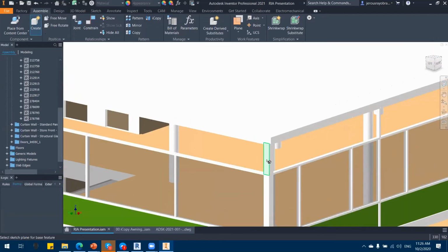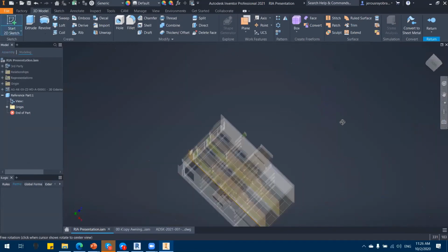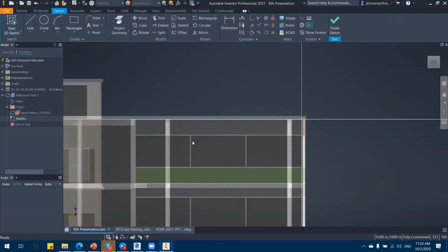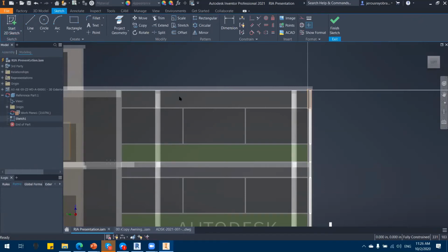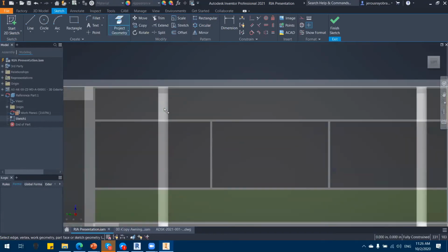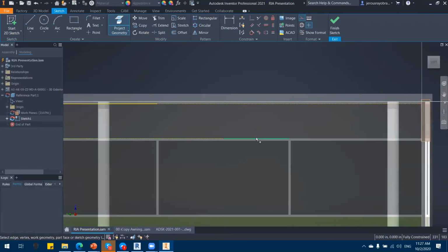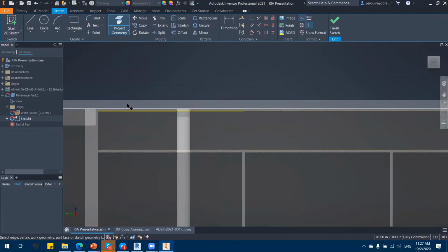In this case here, I'll first create some sketches. I'll create sketches out of this plane. And since I want to place the canopy in this point or in this area, I'll create points of insertion right here. First I can project some geometry. Let's say I'm projecting them as construction lines like this. I'll just do this level. I'm not going to do the other level.